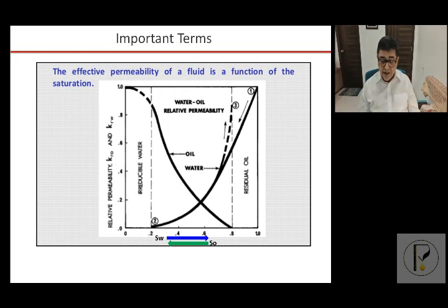Now in the subsequent slides, we will see more of this mobility contrast. This picture depicts the mobility ratio, favorable and unfavorable, stable and unstable. When it is close to 1 or less than 1, the displacement of oil by water is very stable. You can see from the curve, with 1 pore volume of water invading the pores, recovery efficiency is very high.